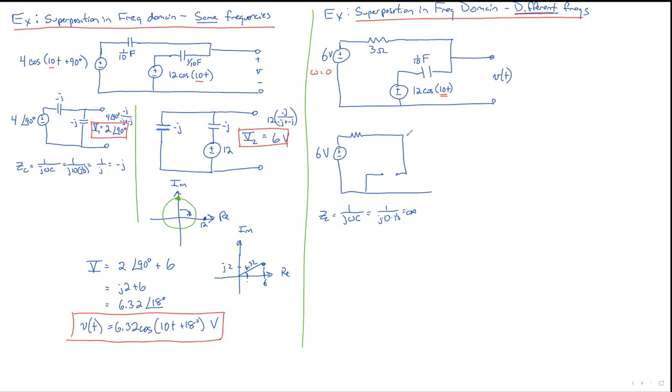And because of superposition, we zero out our voltage source. Now, we could use phasors like we just did, or we could more simply use the fact that this is DC, so we're in DC steady state, so capacitors are opens and inductors are shorts. Either way, we get the same answer. We get the circuit. Where's the current flowing here? Well, it would flow out the more positive terminal, and then it's stuck. So it can't flow anywhere. So that means our current is going to be 0.